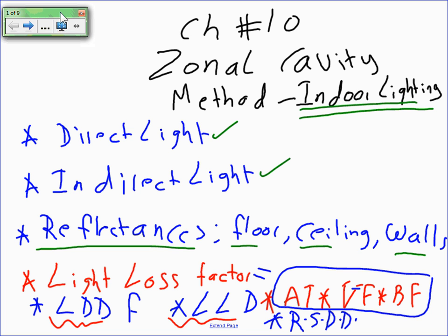As we said before, you have to take the direct light into consideration, the light that comes out of the fixture right at the top of Dustin's head here, and also the indirect light, the light that comes from the fixture, bounces off the wall and hits the illuminated floor. That's why indoor lighting calculation by hand is slightly different than the calculation for outdoor lights, because outdoors, for the most part, you do not have walls to bounce off.